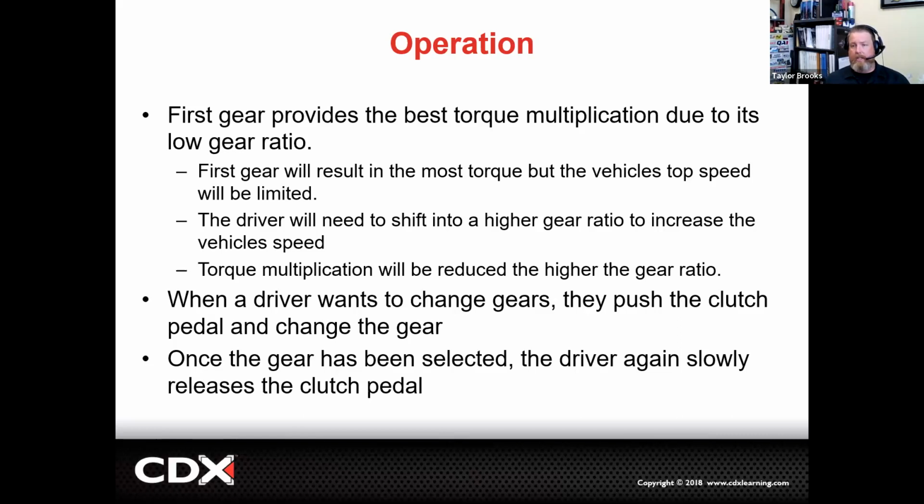When the driver shifts into each gear, we do have to decouple the engine and transmission. So that's where they're going to press the clutch pedal. As they press the clutch pedal down, they're going to take the shifter and put the shifter into neutral. That's a key thing that a lot of people forget, is that oftentimes people just try to shove it into gear. You got to have it in neutral, and then you put it into the next gear. So if you're in first gear, clutch all the way in, neutral, second gear, clutch back out. Not clutch going in and you're trying to shift at the exact same time. Now, a skilled driver can do it relatively quickly, but we need to make sure we're slowing down and engaging it as need be.